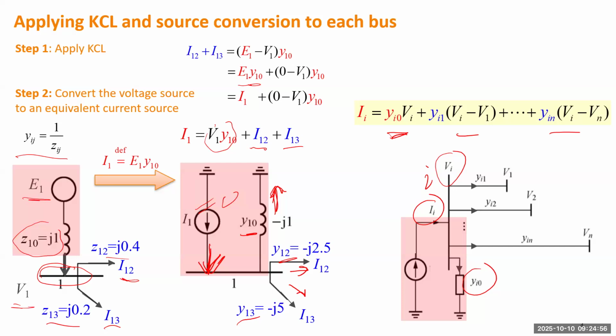But what if between bus 1 and bus 2, there's really no transmission line. There's no branch, no transmission line, no transformer. That's fine. So for instance, let's say between bus i and bus n, there's really no transmission line. There's no physical connection. We simply let this Y be 0. Okay, we still keep this same structure.